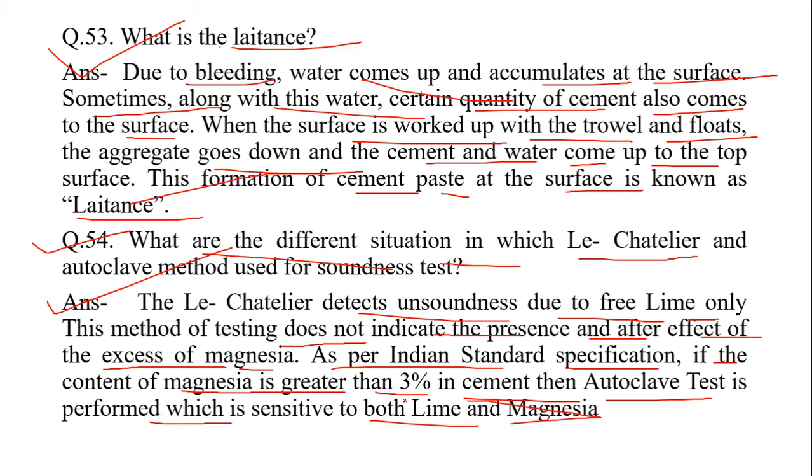Basically, the autoclave test is performed in case of the presence of both lime and magnesia. And the Le Chatelier method cannot be performed with excess of magnesia. In the presence of excess of magnesia, Le Chatelier cannot be performed.